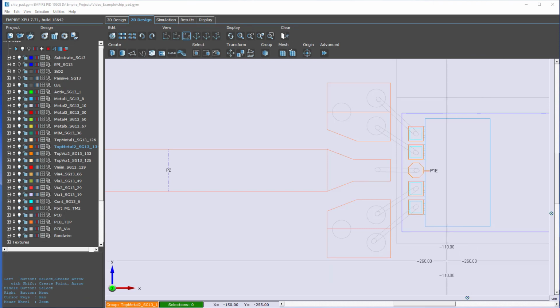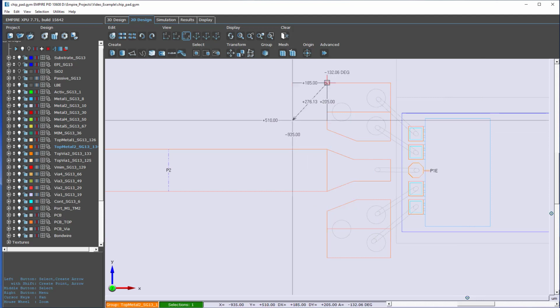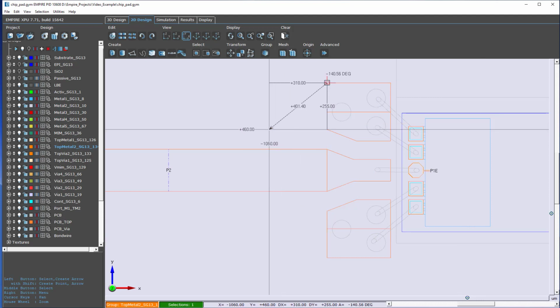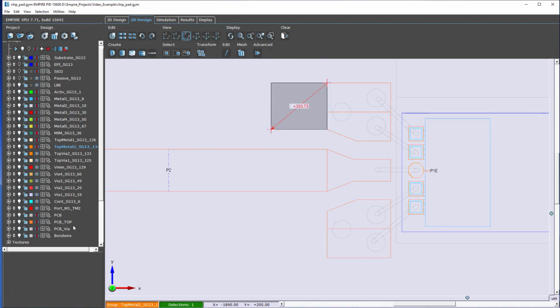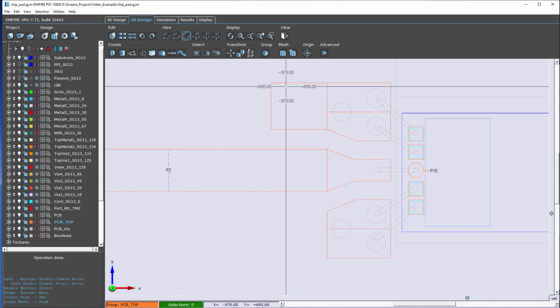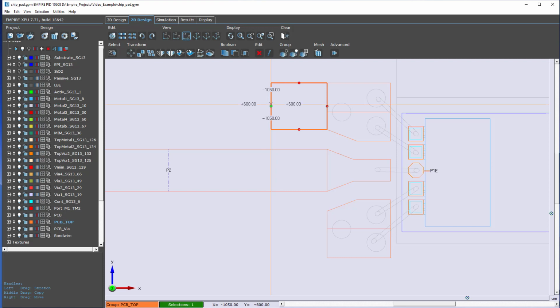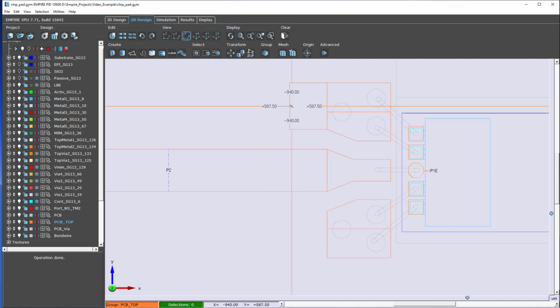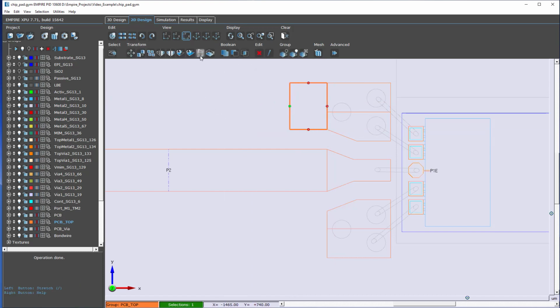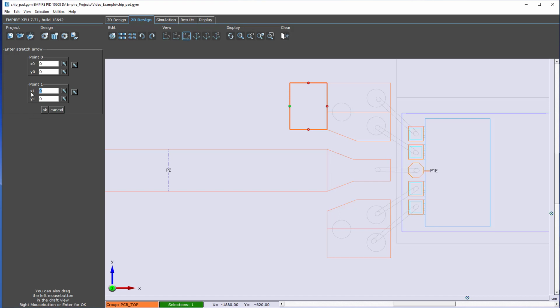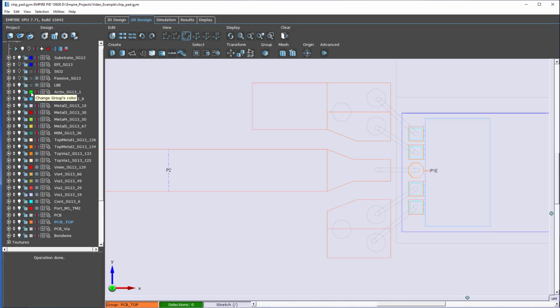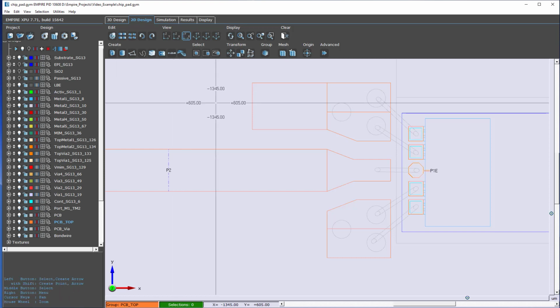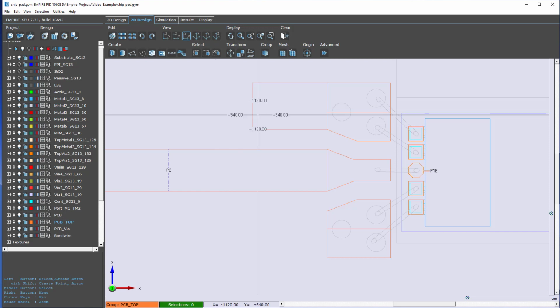Let's look at some more features of the 2D editor. So we had seen that we can create an object just by dragging the arrow with the size that we want. So for example here, horizontal size 300 micron by 255 vertical. Go to the layer where we want to create this object. So PCB top, create, and here we go. If we want to resize it, we can click on that edge. We see the green handle. Now we can easily resize this. Stretch by -200 to go left, and it's stretched. Very easy. There's also parameters, which is discussed in a separate video.